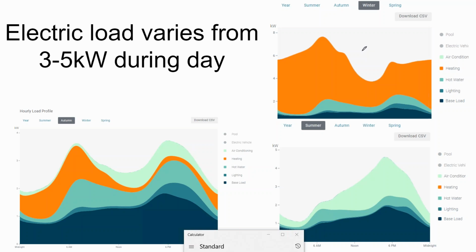But tankless water heaters that surge, tankless water heaters are rated for 20 kilowatts. And so if you do not have a 20 kilowatt surge capacity on your inverter, then you may not be able to have a tankless water heater. It would be a lot better to have a tank and have that tank be a low power level throughout the day rather than have a surge.